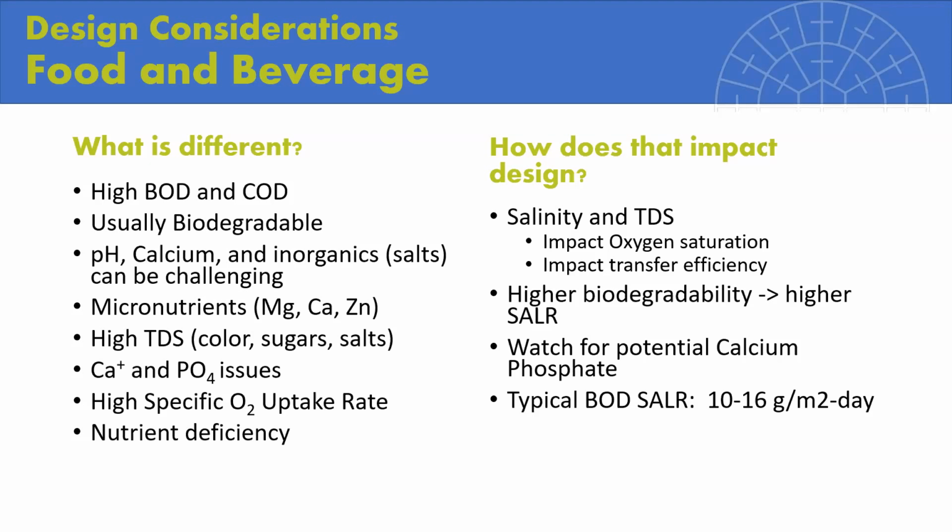For most of our systems, as Kelsey pointed out, our preference is to use disc diffusers, and this is because 100% of the disc area is activated. That is, 100% of the area has oxygen actually flowing out of it. So there's very little risk that the media will impact the top of a disc diffuser.